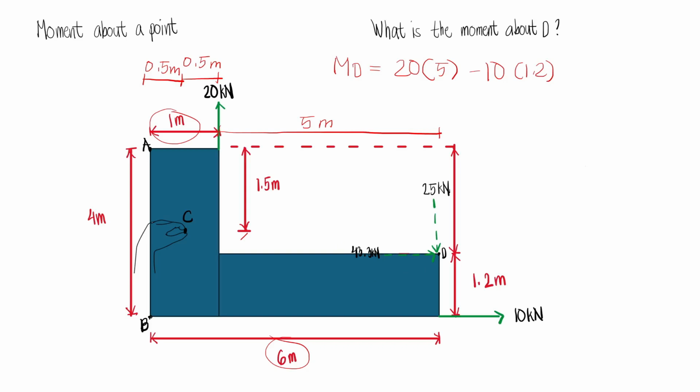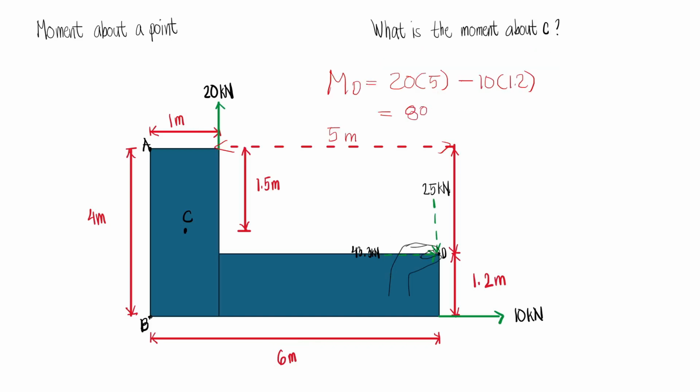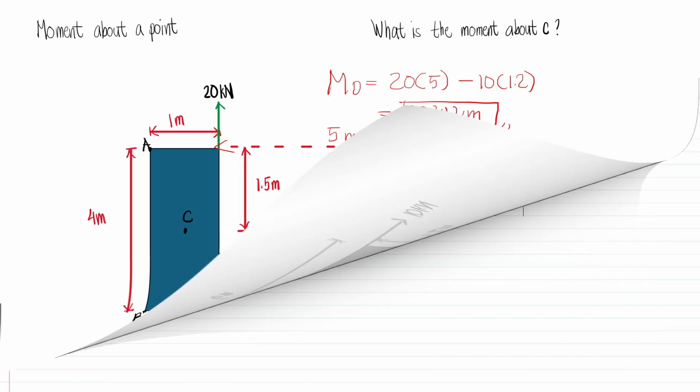Now recall that we initially had 50 kN and then inclined 30 degrees. Now notice that this force directly acts at point D. Now if a force directly acts at a certain point, then that will cause no rotation because essentially you won't have a moment arm for 25 kN and 43.3 kN. If you'll write that down, that will be plus 25 times 0 and then plus 43.3 times 0. And so these will just be neglected. And so adding these, we have 88 kNm. And so this is our answer.